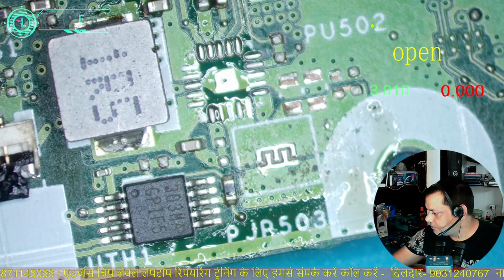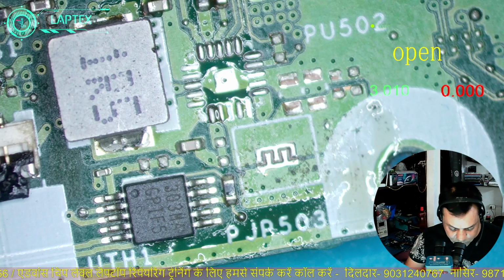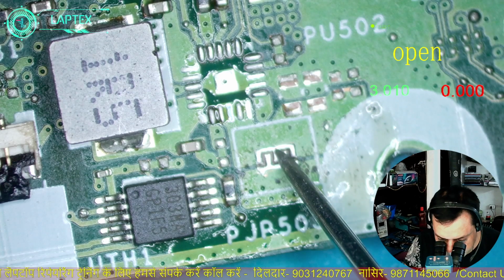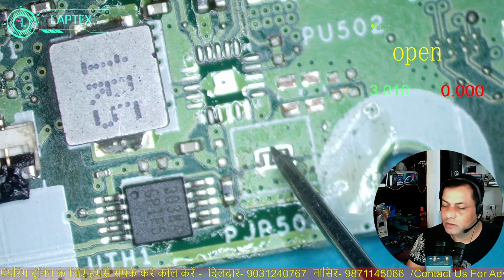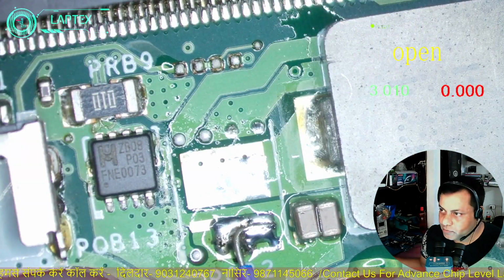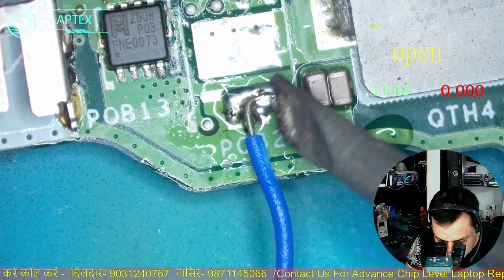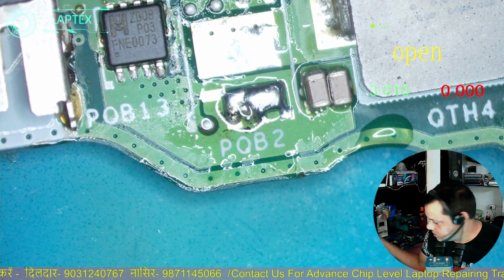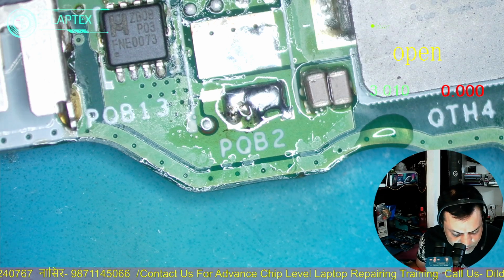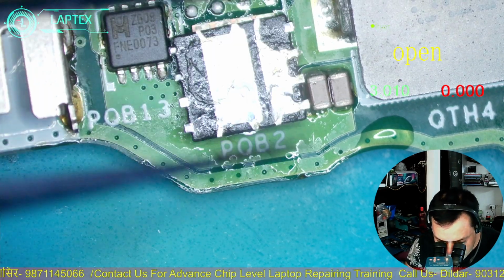Okay, I have removed it. Now shorting must be vanished. Yes, of course, it is gone. So shorting is removed. Now let me remove the jumper wire and solder back the same MOSFET. It is very good because I had suspicion on my MOSFET from the scrap motherboard.